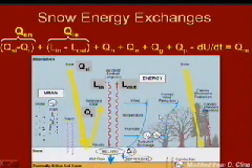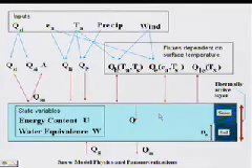I guess the thing that you'll see different about this slide, it's got much more impressive graphics than mine. This slide gives the model physics and parameterizations used in the UEB snowmelt model. I've broken it up so that at the top we have the inputs. It's designed as an energy balance model to take inputs of solar radiation, the water vapor content of the air in terms of vapor pressure, the air temperature, precipitation, and wind speed.